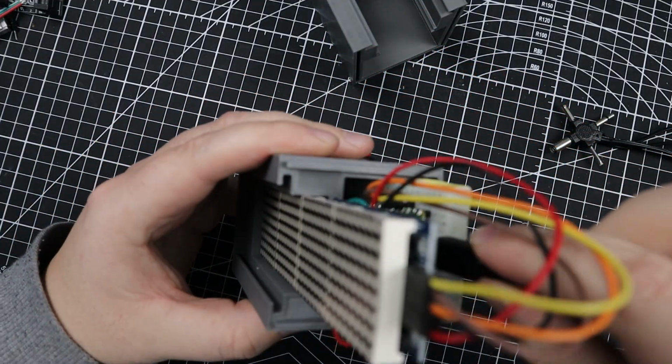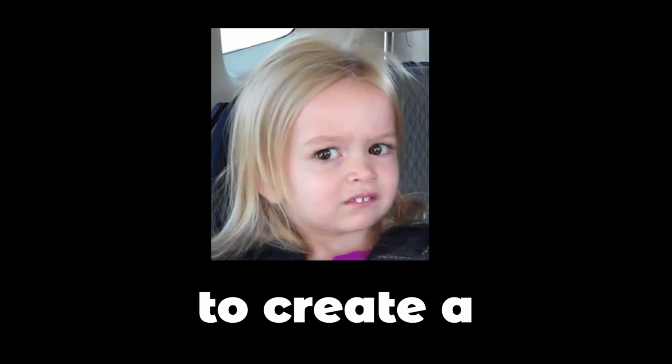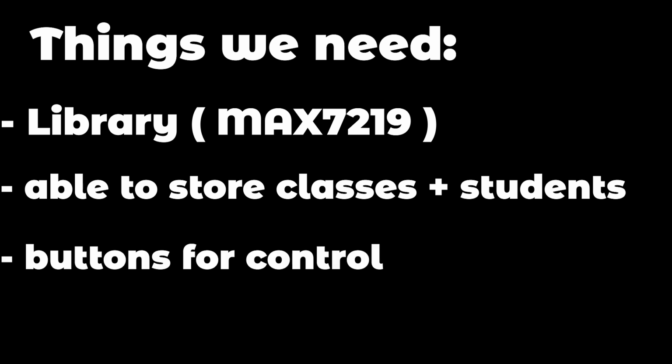Before we close the other half, we first need to upload the code, so we need to think, what do we need to create a random name selector? Well, we first need some library to control the MAX7219 modules. We need to store classes and then assign a name list to each class. For control, we will use the 2 push buttons, one button to go through each class, and then a second button to select a random name in that selected class.